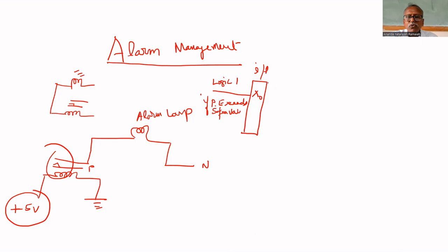This logic 1 can be used to operate the lamp. This is the PLC. In the output module, at Y0, a lamp is connected. This is neutral. This is Y0. Based on that logic, this is 230 volt, let us say single phase. This is the connection diagram.